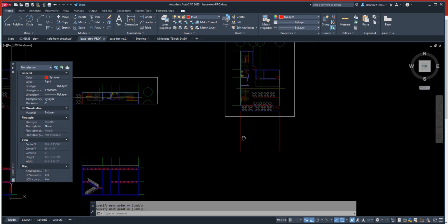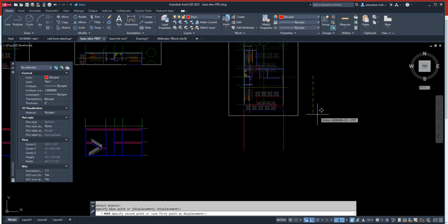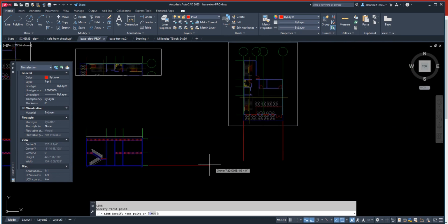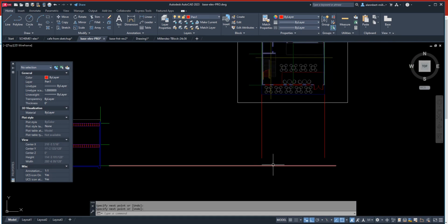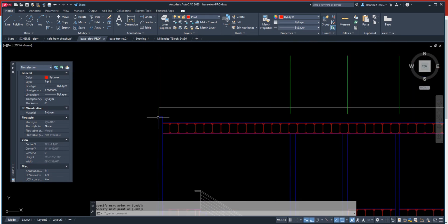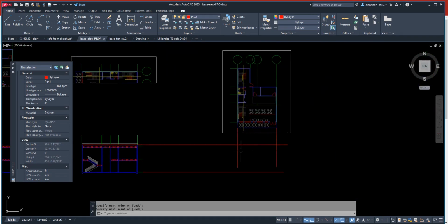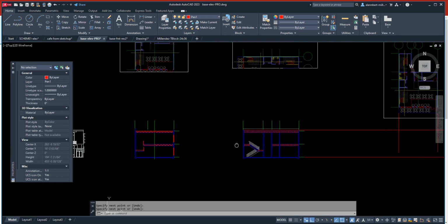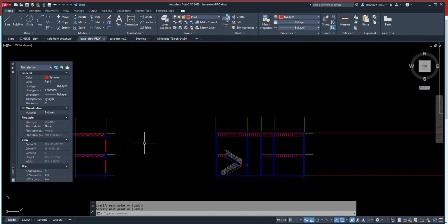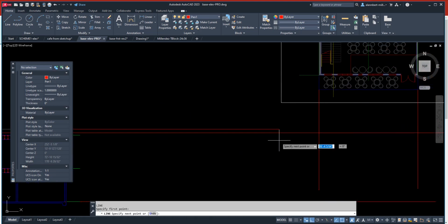And the reason why we wanted to do this on sections is because we're actually going to use the same levels as for our elevations. So that'll be the floor, and for the front elevation, we're going to have this one as the level. So we're going to draw a line from here all the way to here. So that'll be the top of the building. And as you can see on this cross section over here, we have a parapet that is 30 inches from the roof line. And that's this gray area over here. So we're gonna also do that thing and then copy it here.